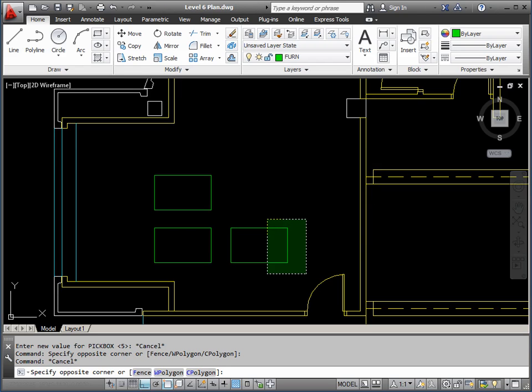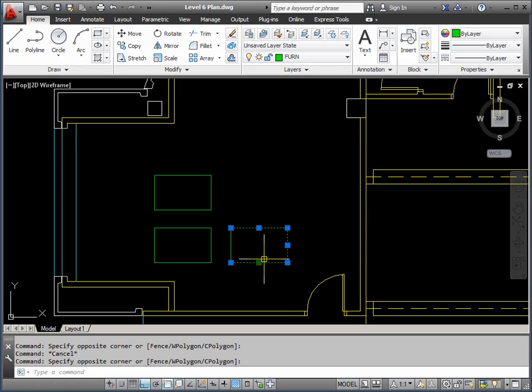Okay, do the similar shape, but you'll see that it takes in 3 lines this time. Okay, it took the one that was completely in, but it also took the 2 that were cut by that green shape. And that's termed a crossing window. It's much more powerful.